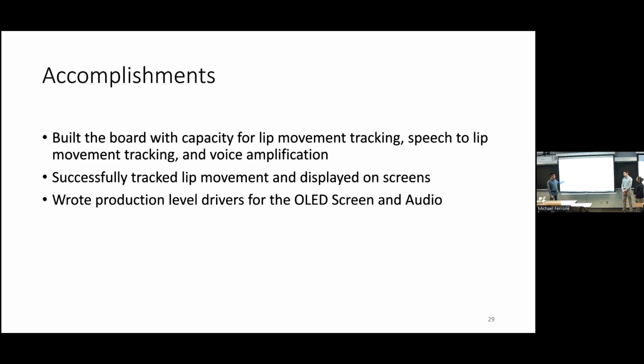So in terms of drivers, the drivers available as open source on the internet for this type of screen are 8-bit drivers. For this one, we need a 9-bit driver, so we needed to write it. The first bit is a data selection bit, which is not available in the open source, but we need it for our screen. So we had to write one on our own rather than just using open source.